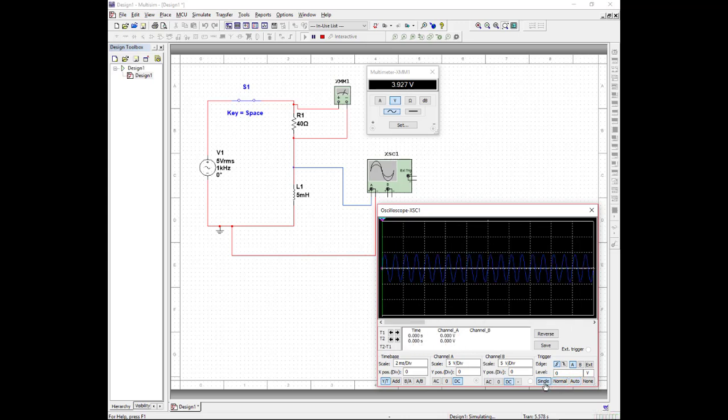Okay, so if I single trigger, what it's done now is it's looked at the wave. Okay, and I'm holding this point, but if you look at the scroll bar here, it's getting smaller and smaller. That's because the signal is running out to the right hand side. So if I take this and I go to the right hand side, it doesn't look like the signal changing, but it is actually changing.